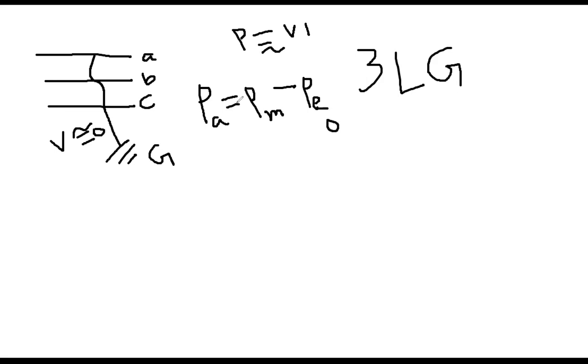So then what is the accelerating power? Pa equal to Pm. So what will happen? Your generator was running at this speed, it will speed up very much. And if the speed goes very high, the frequency will go very high. That is the impact. So anyway, this is the example of a 3-phase to ground fault.